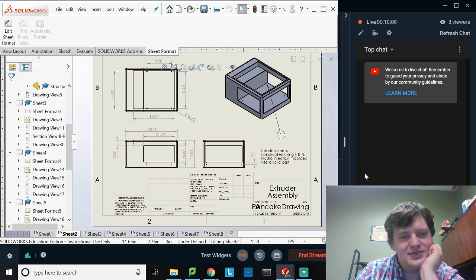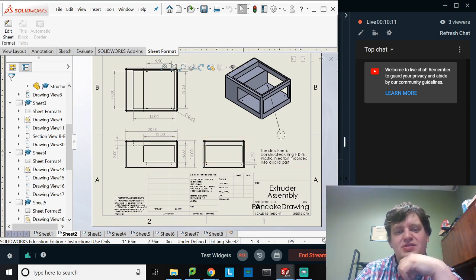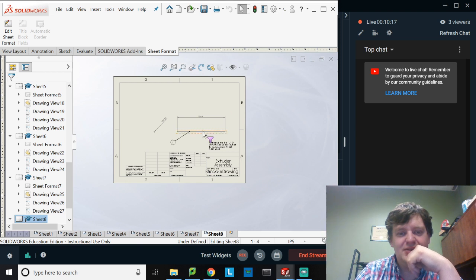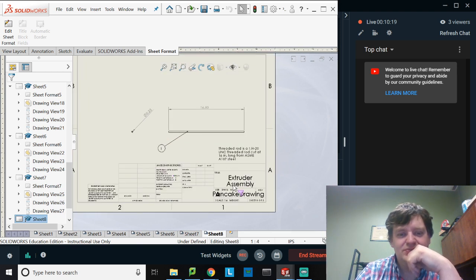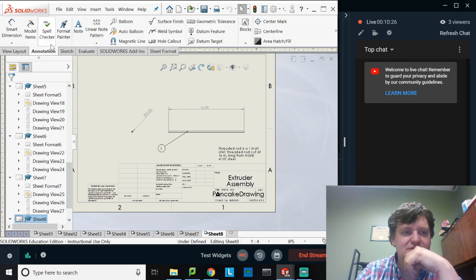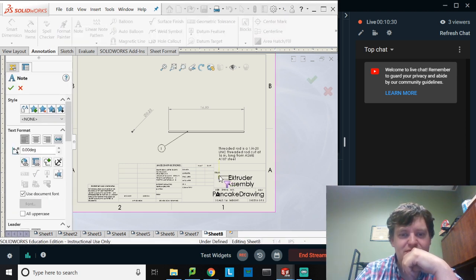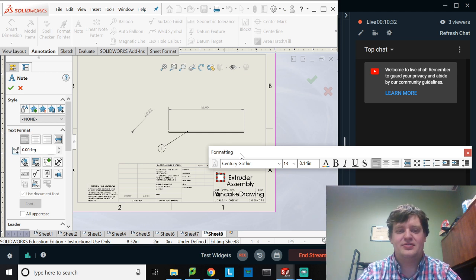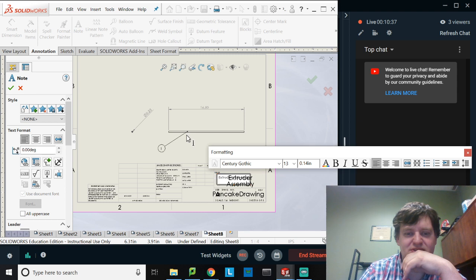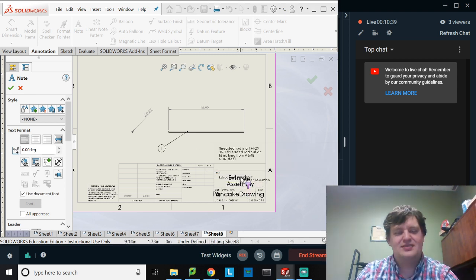I guess that's about all I wanted to cover for this video, was just give you a little bit more detail on how to make this look. You're going to have to type in the titles manually. You'll have to create a title block, annotation, go up, create a note, draw it right here, actually write it in. Because for some reason it is not liking that.